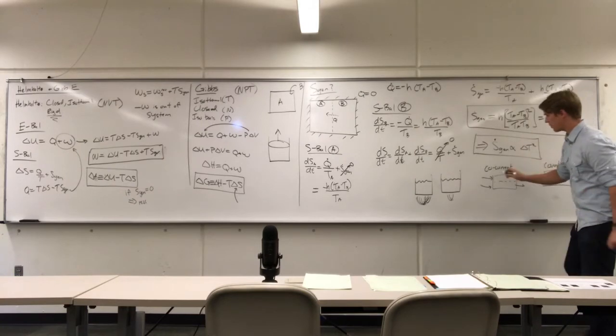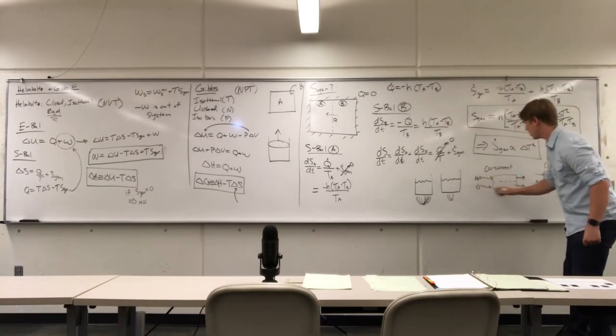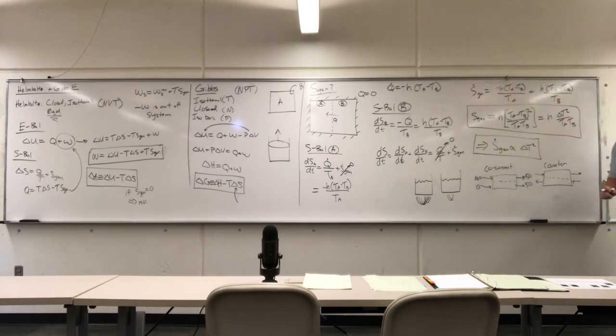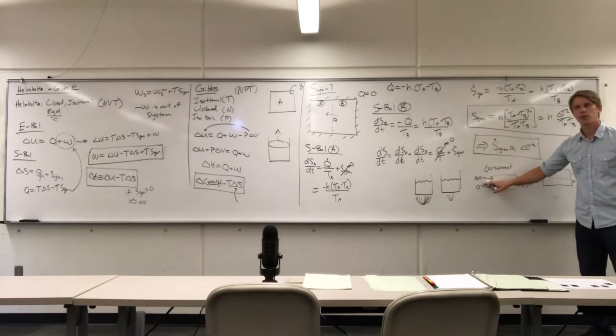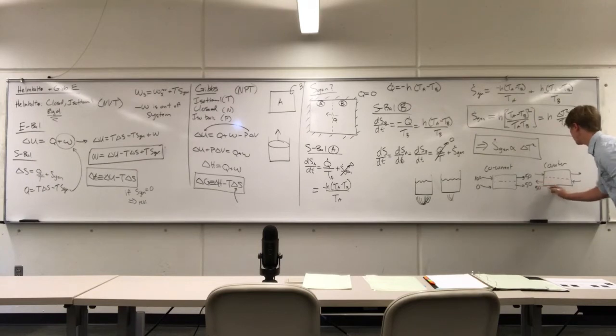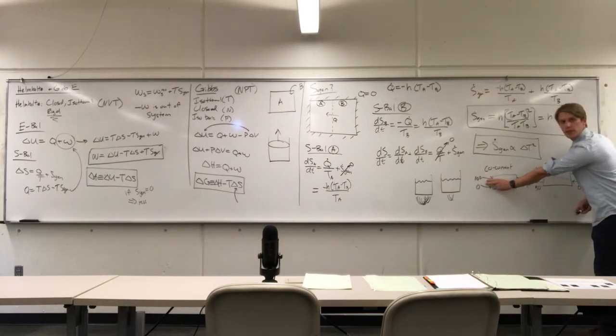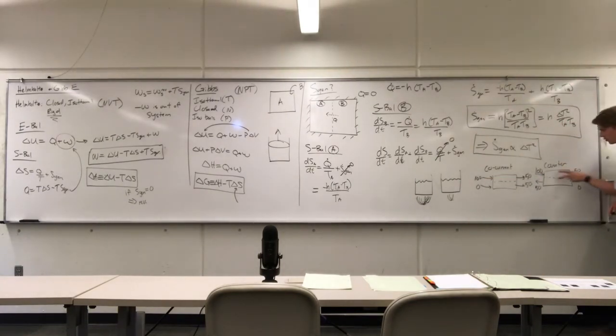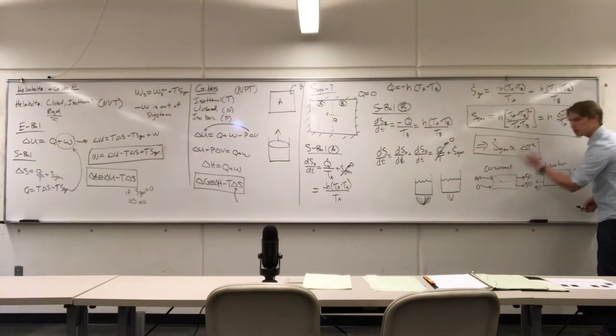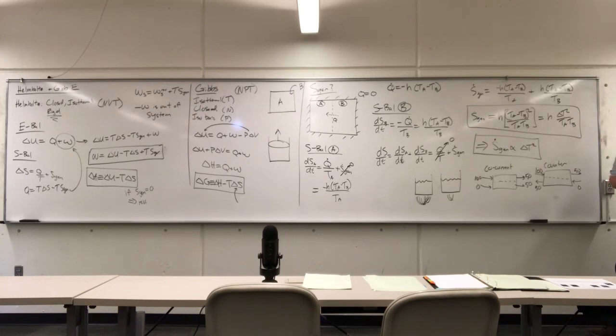So let's say, for example, let's just hypothetically say that this is at 100 and this is at 0, and then at the end, we want them all to be 50-50. So in this case here, our gradient is 100 degrees C at one end. If we do it opposite, this one has to be 50, this one has to be 100. I'm just flipping the bottom stream. So in this case, the gradient here is 100 degrees, and 100 squared is substantial. In the countercurrent case, the gradient is always 50 degrees, and 50 squared is less than 100 squared. We're still generating entropy in both of these heat exchangers, but we're generating more entropy here. So from an energy balance and an entropy balance perspective, it makes sense to do countercurrent too.